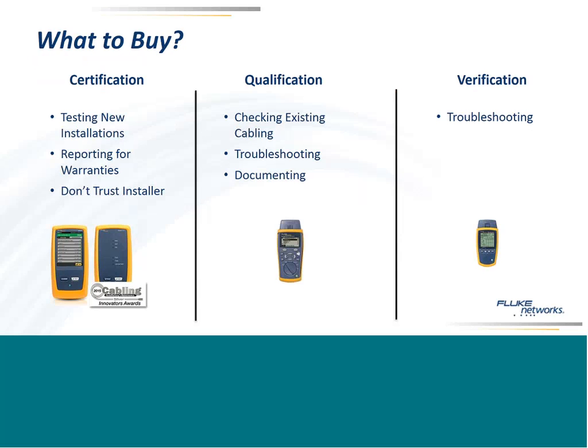Anyway, so what do you want to buy? A certification tool is really what you need if you're testing new installations. If you're building a new building and you're putting in new cabling, I'd recommend you buy a certification tool, or you hire somebody to do it, or you rent one of these tools. They're easy to rent, by the way. They're not hard at all. Also, the test results that you get from a certification tool can be given to a cabling manufacturer, and they will certify your cabling then for 10, 15, sometimes even 20 years of use, goodness. And the third one is if you don't trust your installer and you want to go around behind them and see what they're really doing, then you need a certification tool.